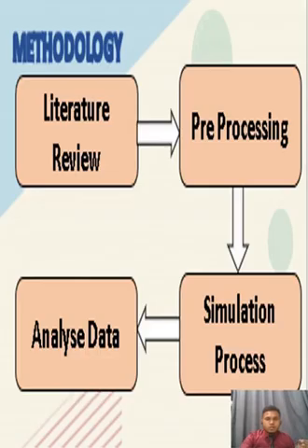The pre-processing is done by using LS-PrePost software. The type of input file is a K file, and it can only be read and processed by LS-DYNA software. LS-PrePost will be used to create the material model of steel plate of desirable properties and thickness. After the boundary condition is set, the model is drawn according to the boundary, and the properties of the material are specified in the details of the material model. The completed material model will be exported as a K file to be processed in LS-DYNA.